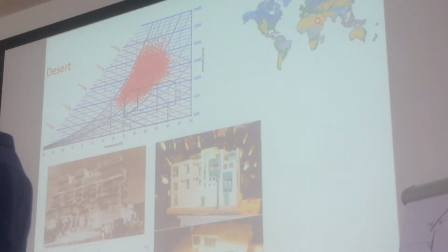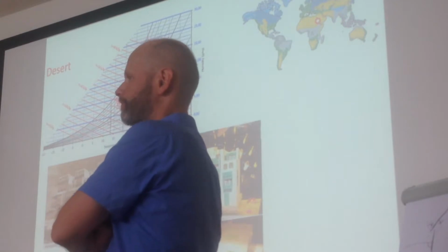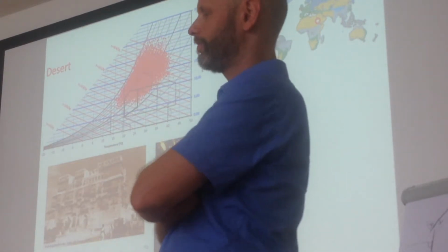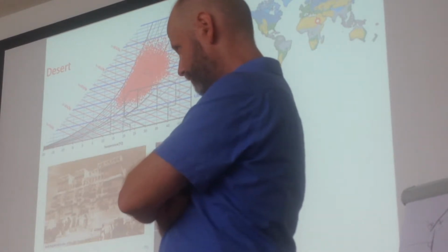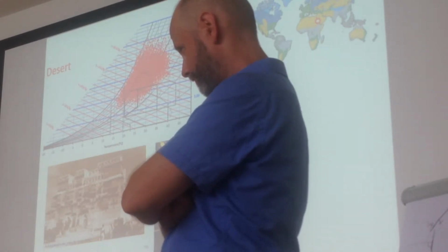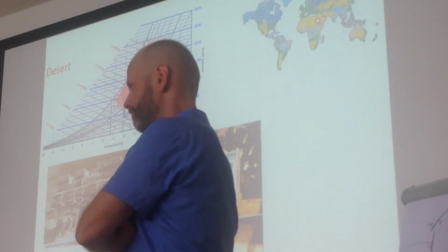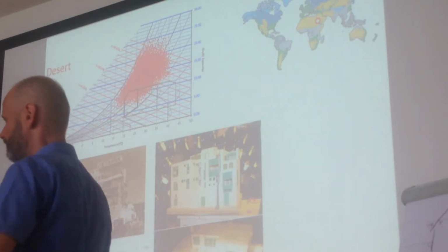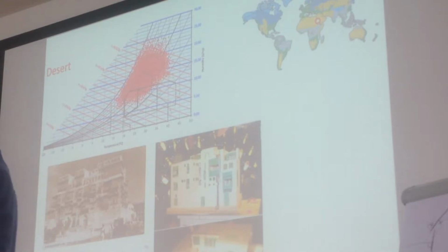And if you consider the climate here in Central Europe, you said the maximum should be 26. If we have an outdoor temperature of 37, 28 is acceptable, definitely. But what makes the big difference, and there have been a lot of studies and surveys, is if people can control it by themselves. If you control it by an automatic system, people will be very scared and will complain at any time. If you say, you can control the windows, do whatever you want, people are very forgiving.